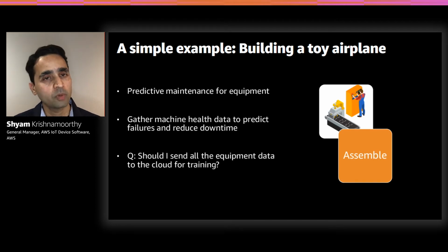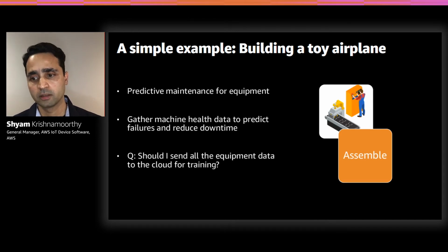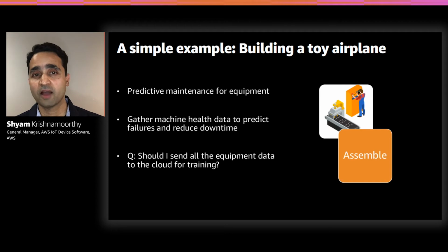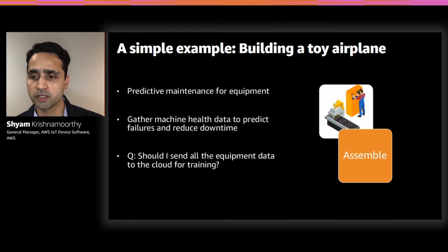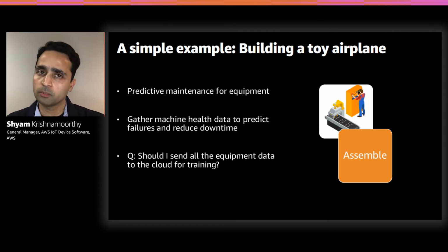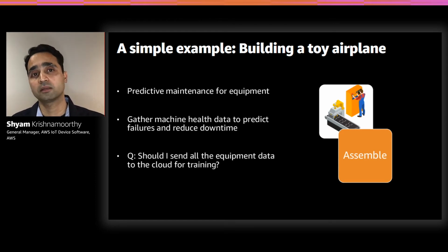So that sounds great, but we've got some interesting challenges here that we want to think about. That data, do I want to actually analyze that data locally, or do I want to send that to the cloud? If you think about vibration sensors, for example, as a technique to solve this, if I'm collecting half a kilobyte every millisecond, and I want to send that to the cloud, within a day I have many gigabytes of data. And a lot of that data might be actually just sensor noise, calibration issues, or little spikes that actually don't have a lot of meaning until you've sort of smoothed it, you've done some filtering, and so on and so forth. So you have to think about, okay, what part of that processing do I want to do in the factory itself locally? How much do I want to send that data to the cloud?